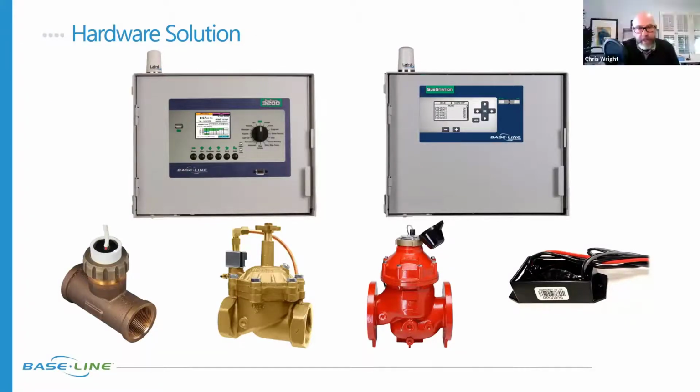And are those attached to a mechanical float? No, it's all electronic. It's a 4 to 20 milliamp device that we're getting a signal from. If this project happened this year, we'd be using our pressure transducer instead of their sensor, but that's another story. Right. And what makes this all possible, guys?